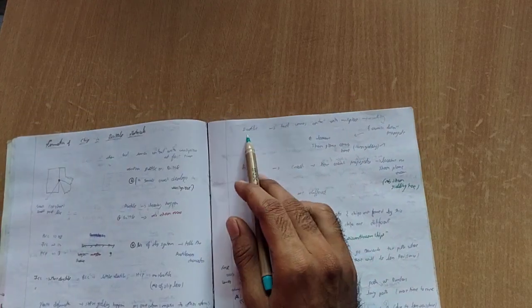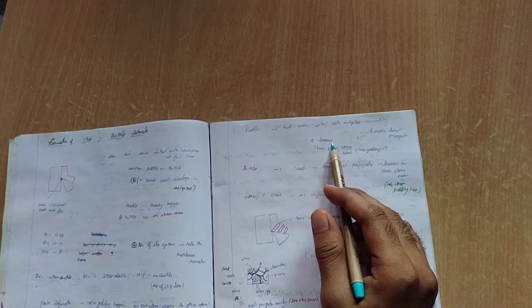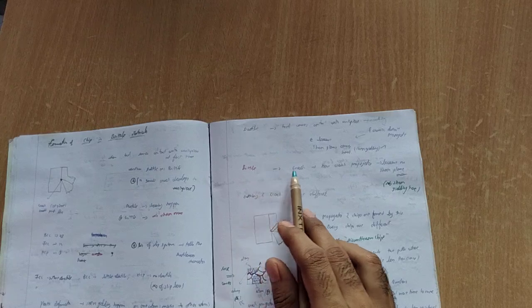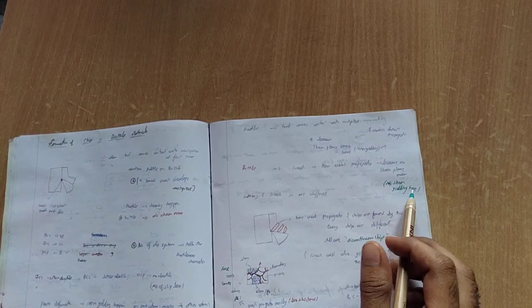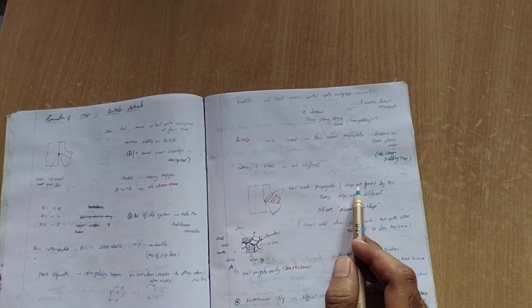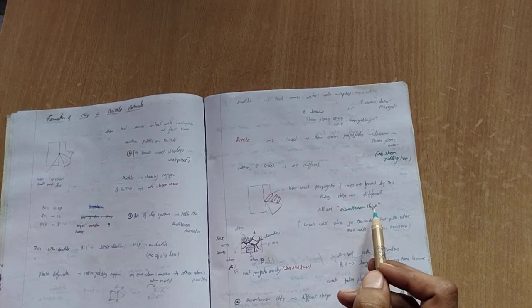So next thing you can see, when the ductile tool comes in contact with the workpiece, crack initiation and propagation lead to fracture, and a slip plane comes and shear yielding occurs. But in brittle material, a crack happens and propagates, but there is no slip plane and no shear yielding occurs. It means cutting and crack are different. In this, the crack propagates and chips are formed, every chip is different. That's why it is called a discontinuous chip.